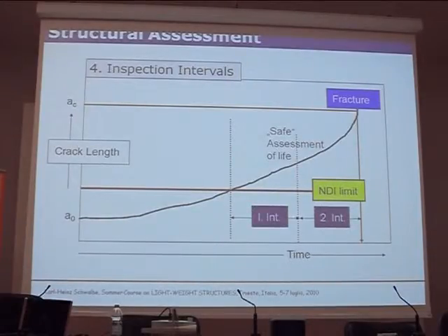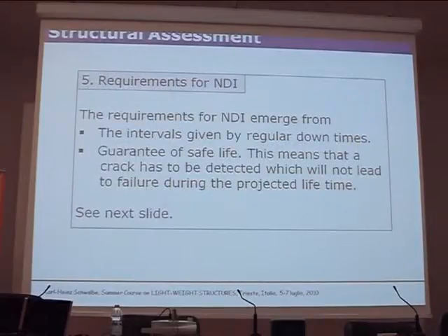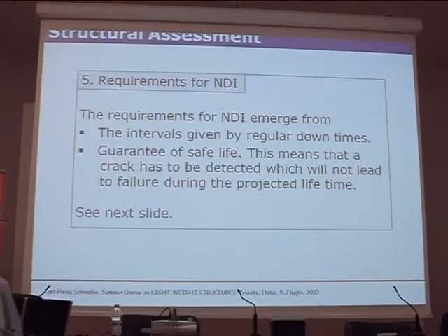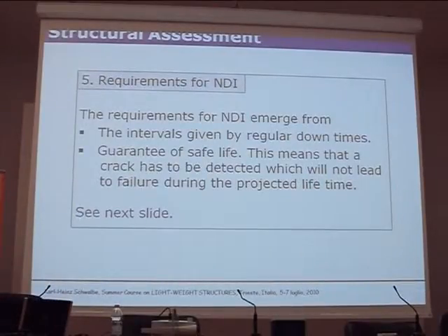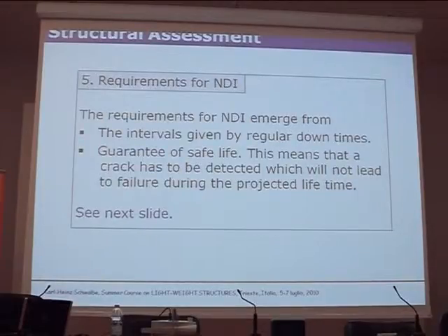So you have the first interval and the second interval. And the requirements, now the requirements for NDI emerge from the intervals given by regular downtimes. This would be the most convenient thing if your component or system, be it a chemical plant or railway equipment or aeroplane, has to be grounded anyway for any other kinds of repair or regular thing. It would be ideal to perform the crack inspections at the same time.